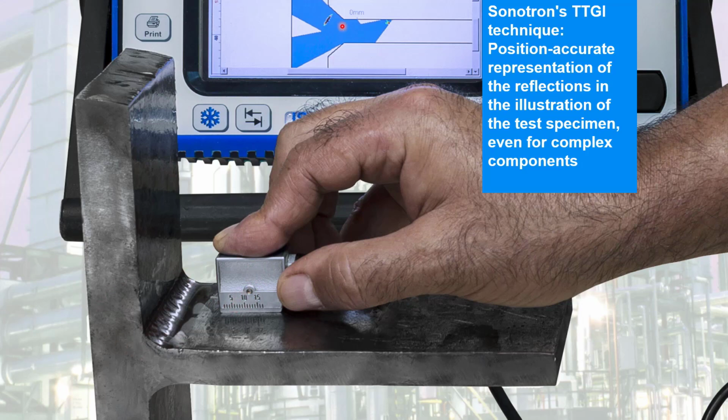And what you see on the top here is the content on the display. Of course, you have to key in the thickness of this part. You have to define the weld somehow. You can also, by the way, define the weld preparation if you want. It's also shown here, not in this case, but it can be done. The front edge of the probe is here, the 0 point, which is marked here.